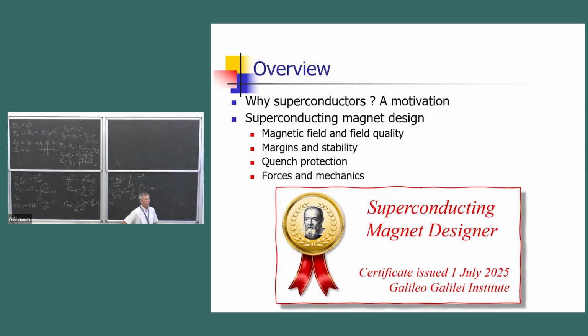What we usually do is, take the LHC as an example. The idea was to have the tunnel, 27 kilometers. You have the beam, you want the energy, so you want the field. If you want a certain field and you want to use a certain material, niobium titanium, you end up with these equations, with a certain set of current densities and coil cross section, and then you have to realize that in practice.